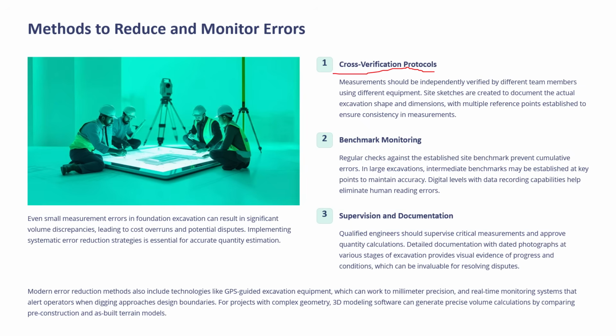So measurements should be independently verified by different team members using different equipments. Site sketches are created to document the actual excavation shape and dimensions, with multiple reference points established to ensure consistency in measurements.